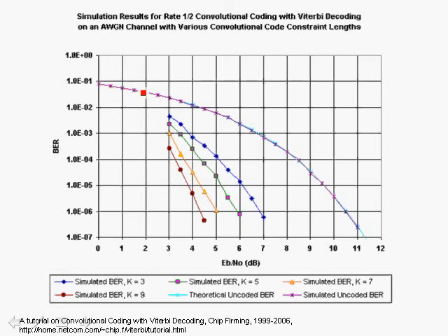The first curve that's shown over here is the case where you do not have coding, for example a BPSK type simulation, where you have just +1, -1 or binary encoding. This curve shows the probability of error versus the Eb/N0, and this matches exactly the Q function.